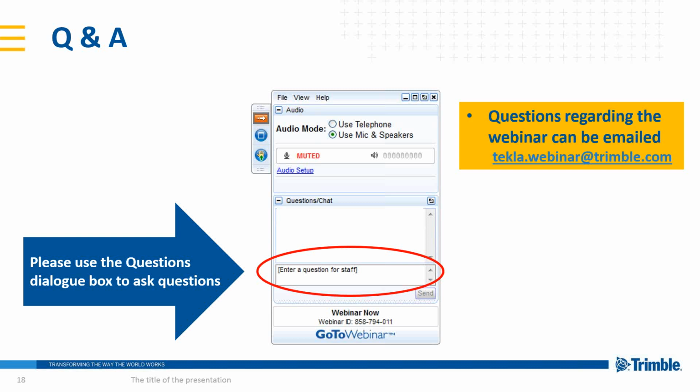Laser projectors can't be repaired on location. If you have a spare projector on site, you just change it. Switch off, disconnect cable, open bracket, change projector, aim system at workplace, close bracket, connect cable, switch on, recalibrate, and work on. Done nearly as fast as I'm telling it.